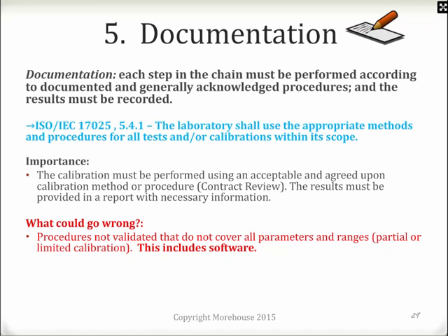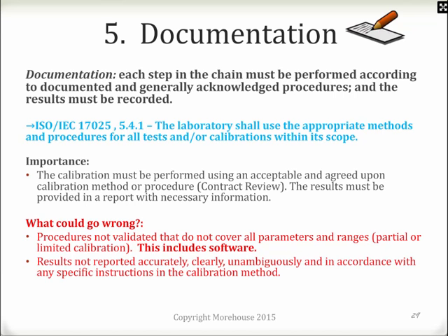Well, procedures not validated that do not cover all parameters and ranges, partial or limited calibration. This includes software. So you send your force transducer off to a manufacturer, and it's a 150,000 pound transducer, and they calibrate it. They only apply 50,000 pounds of force and interpolate the rest. Now that's an example of you're guessing. It needs to be tested.